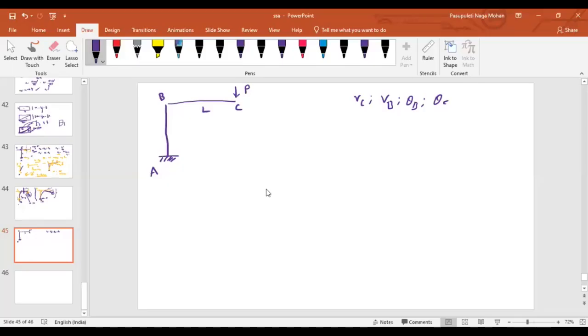Now, let us separate the members as usual. Here, if it is P, whatever the forces about this point, can you tell me? Whatever the forces here, forces will generate or not at this point? Whatever the vertical force, horizontal force and moment that develop here? Upward vertical force, P. Moment, anti-clockwise, whatever that magnitude, PL.